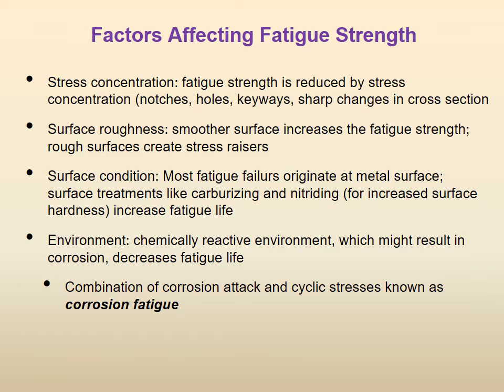The slip band stage is very slow. It takes a longer time to form the crack nucleation. And once the crack is formed, then stage 2, it keeps on growing, but it is stable. Even though it is growing, there is still life. We will see later on that once it reaches a critical value, then there will be sudden catastrophic failure after some time.